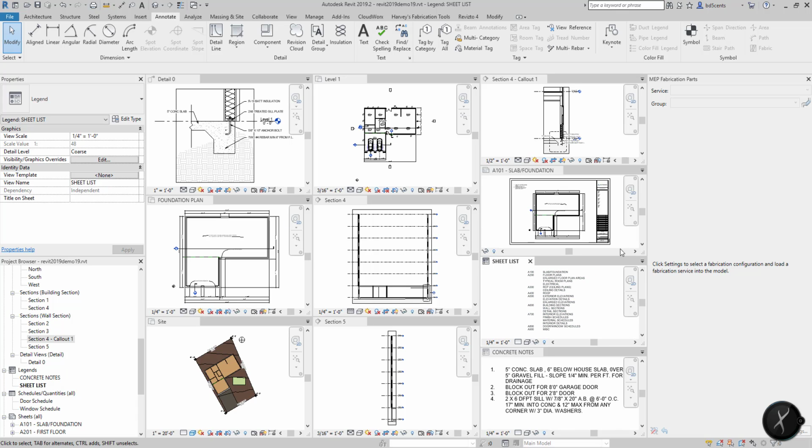So I've gotten a lot of work done. Remember, each of these drawings are all part of the same file. They're all tied together as a database of information. You've learned how to create detail views, apply 2D detail components to sections and detail views, how to create filled regions, and add dumb text annotation. And we'll explain what I mean by that later.